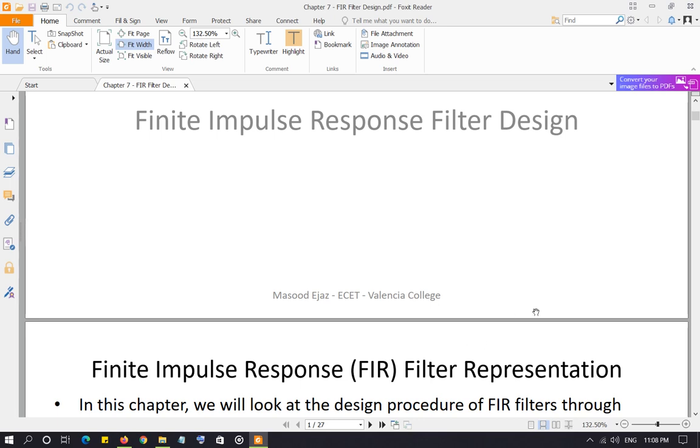And the other difference between the two filters is, of course, in the difference equation. The difference equation of FIR filters, as we discussed for any other DSP systems in the initial chapters, only has x and previous instances of x, that is input, but it does not have any previous instance of the output.